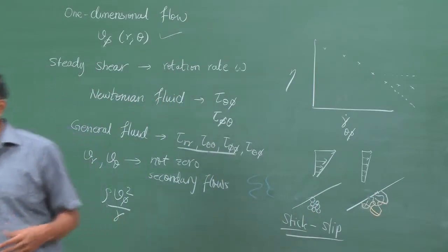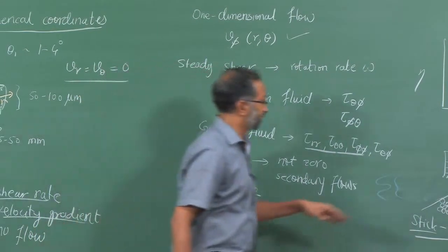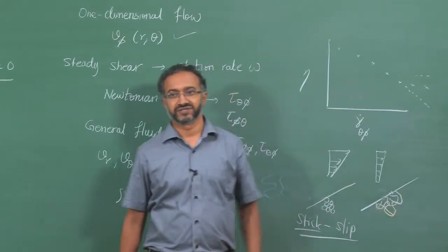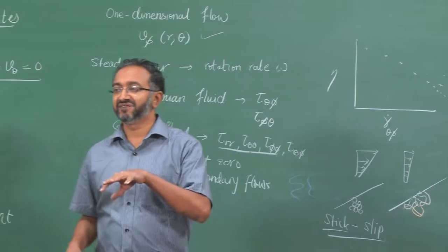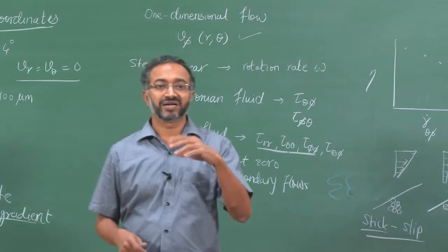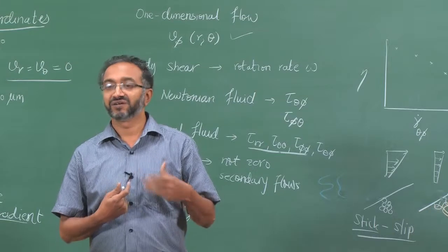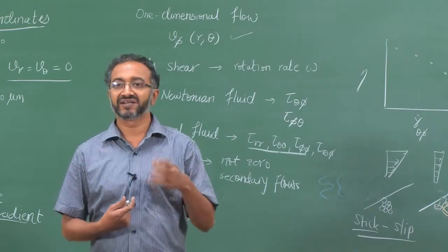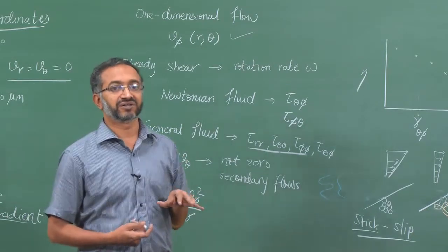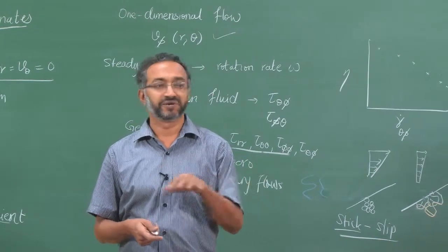The other way of course is to enable more adhesion. One easy way of enabling more adhesion sometimes is to induce a small amount of roughness, which will not induce enough secondary flow to violate my one-dimensional flow assumption, but at the same time roughness usually will increase adhesion between two materials. So, slipping of materials will be less if I increase roughness. And again, in all of these cases we must always make sure that the qualitative features of the results remain the same with all these different types of geometries.